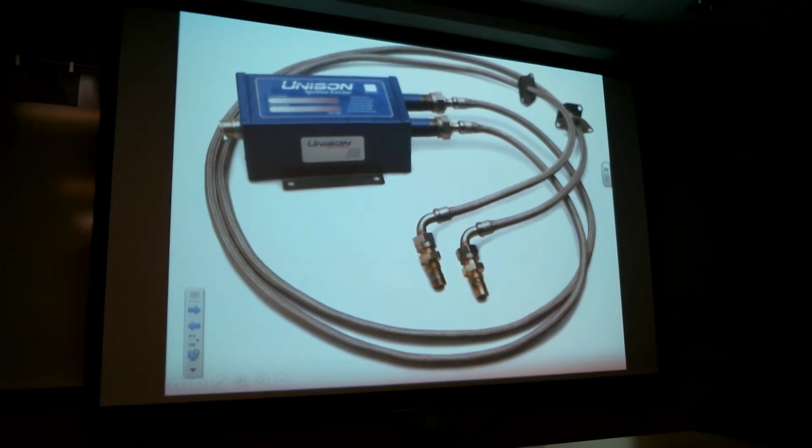Down on this end is the electrical input, so this is going to be ship's power. It's going to come from the bus bar and switch for the ignition. Then you've got a few of these little guys here. They go through firewalls and baffles just to make sure that they go through a sealed area, so you don't have heat running through there where it's not supposed to go. Okay, the igniter. You got the lead, and you got the ignition exciter box.